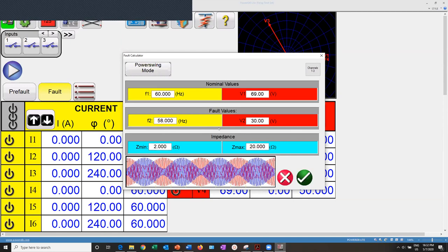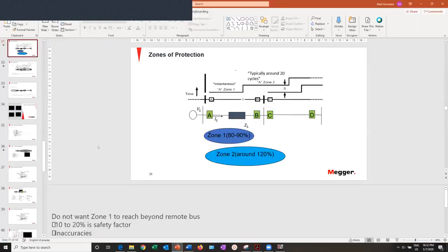Okay, yes. So, well, the answer here is, if you have a proper coordination study, the beauty of protection these days is that there are so many electronic tools, simulation tools that you can use, and they're very, very accurate to properly coordinate this protection. So remember that we are allowing 20 cycles for this zone to operate. It will operate, and I'm pointing here at zone 2.